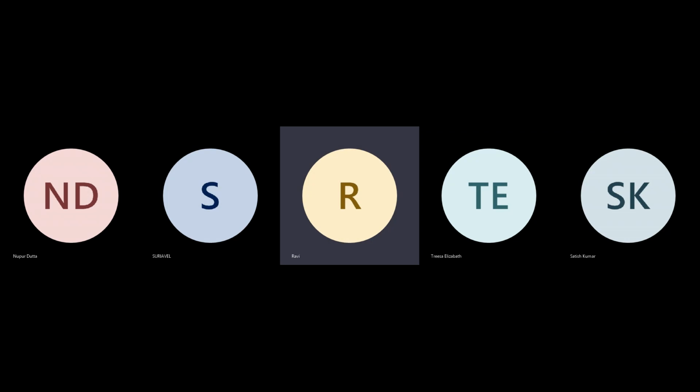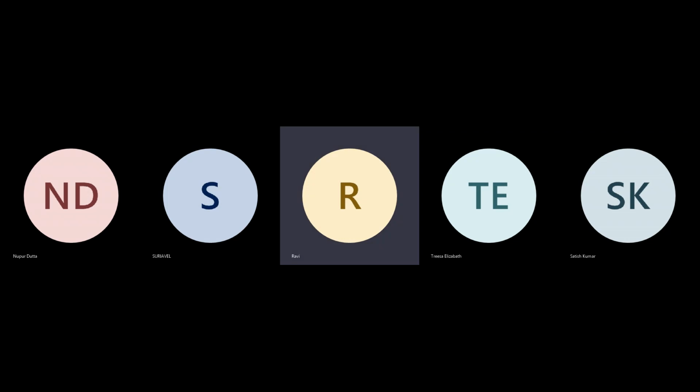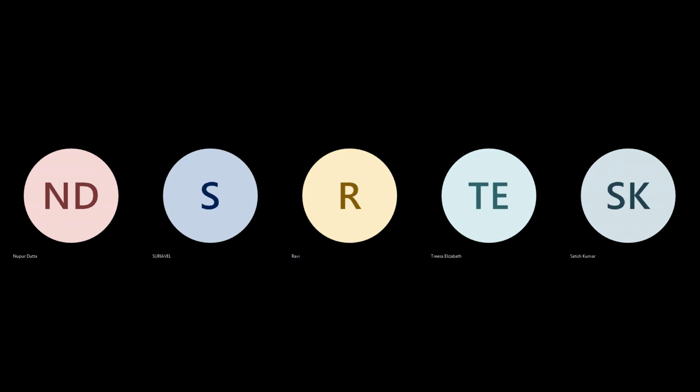So we cannot clearly say that the lower temperature corner will be critical or the higher temperature corner will be critical. It depends on the library, how it is positioned, your net length, everything. But both the corners became critical for 90 nanometer and below.